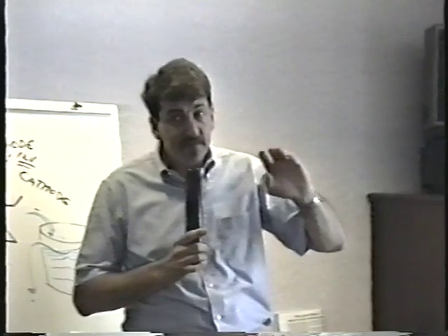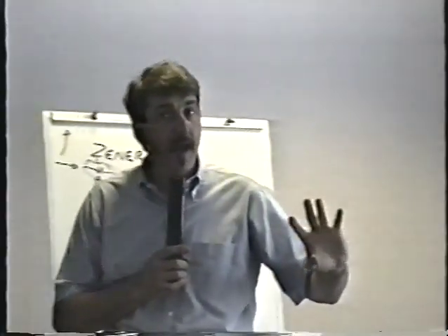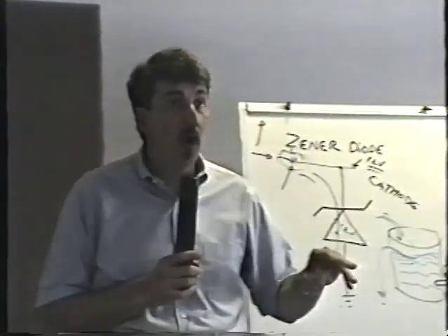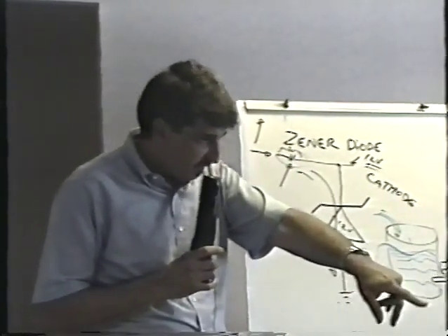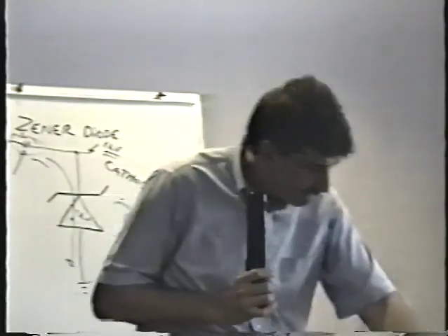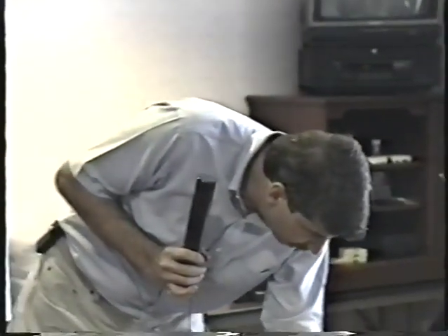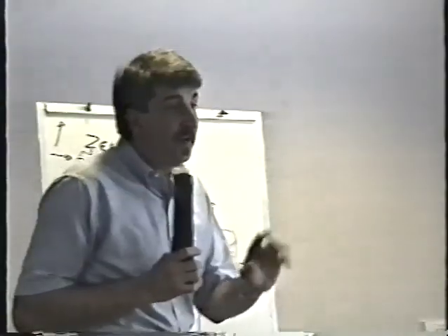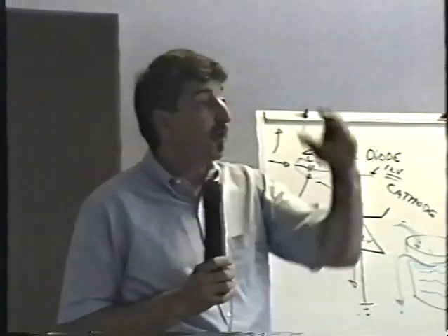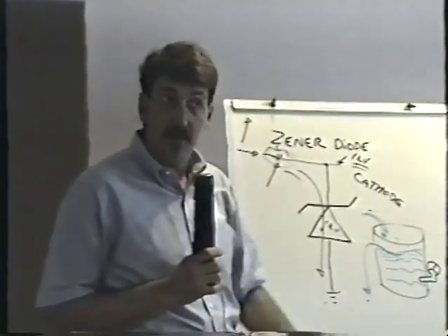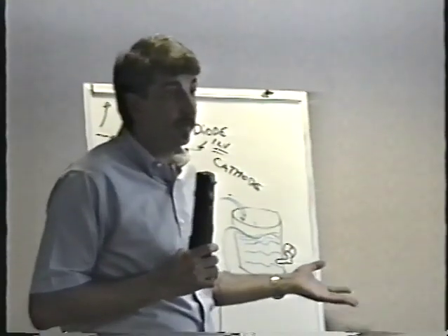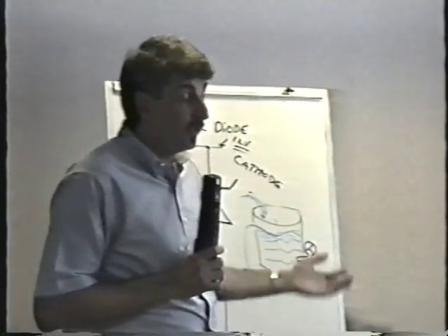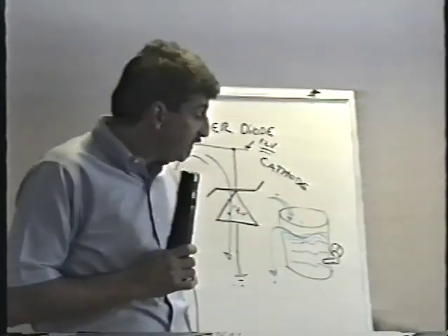If the voltage rating is not listed on the schematic, which it sometimes is but not always, you get the part number off the Zener, like 1N4764, or whatever the part number is, and you look it up in your ECG book. Your ECG book tells you how many volts the Zener is supposed to be. Big advantage, because without the ECG book, you might not be able to figure out what the voltage is supposed to be. So, Zener diodes.